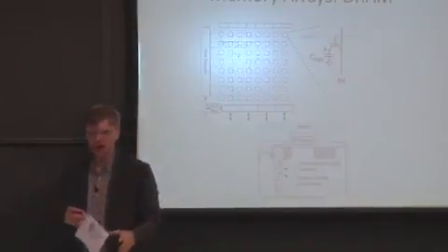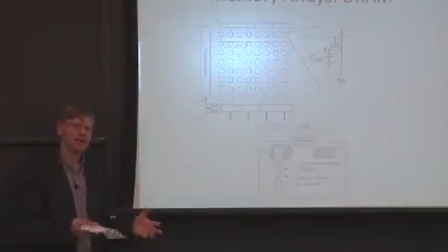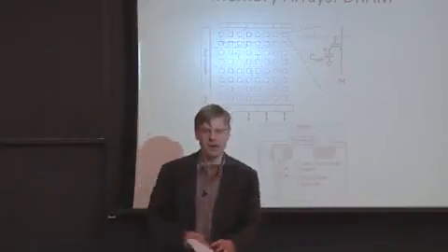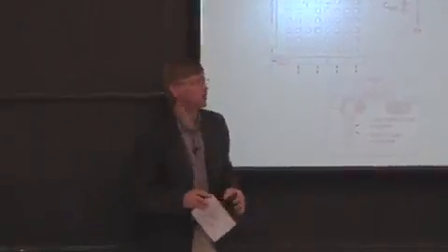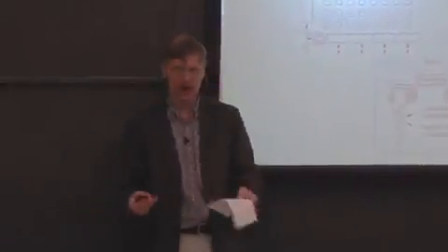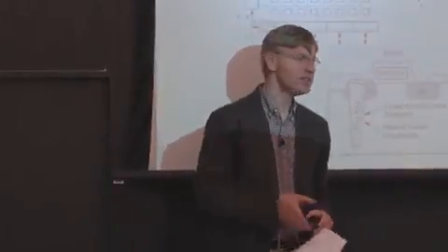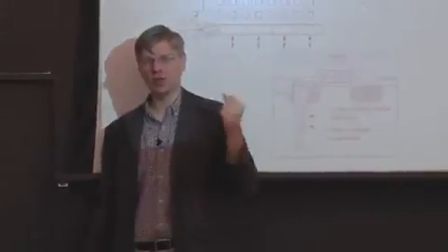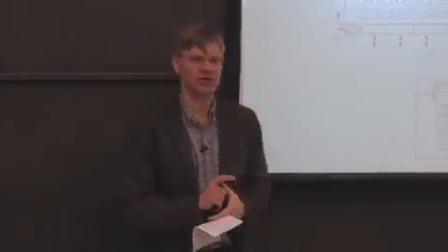Okay, so what are the advantages of DRAM? Why are we even talking about DRAM? Well, it's a lot easier in DRAM to have large amounts of storage. You can have big amounts of storage in the same area because instead of having, in SRAM, 6 or 8 transistors for each cell, we now have one transistor and one capacitor. So it's actually less. Now, how does this circuit work?